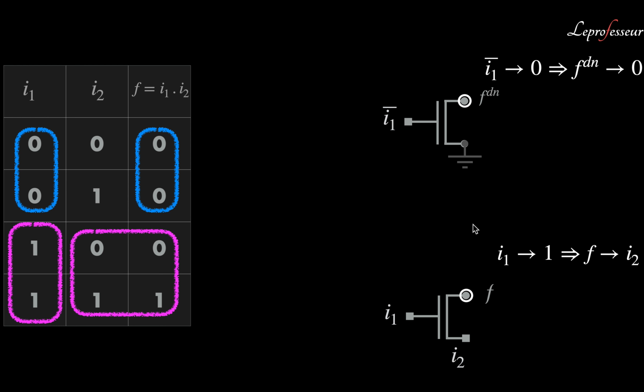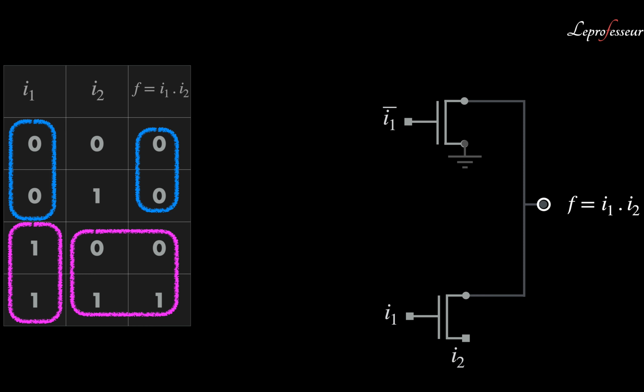We got at least a configuration for the circuit, how we can connect it. Now remember that the pull up and pull down networks are joined together, and if we connect both terminals together, then we get the desired output of the AND gate. Now I1 bar is nothing but the inverted value, so we put an inverter.